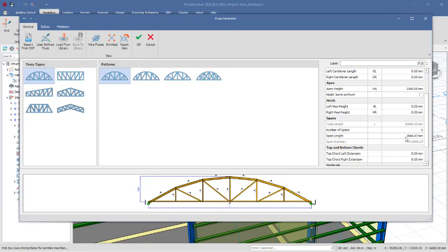And so for you to define the spacing of a purlin, let's say I wanted my purlin spacing to be less than, let's say, 900 millimeters. So I will come to this provision where I have number of spans. I will increase the number of spans for this, for the 6 number of spans. See the span length here, which is the spacing between the purlins. It is 2666.67 millimeters, all right.